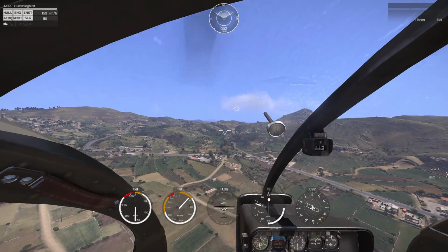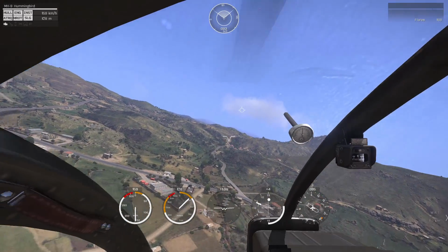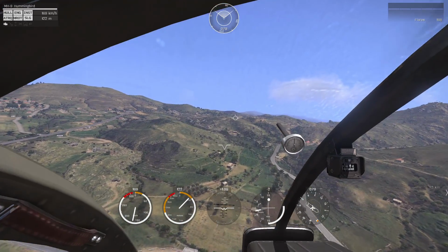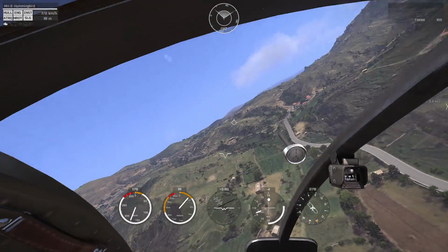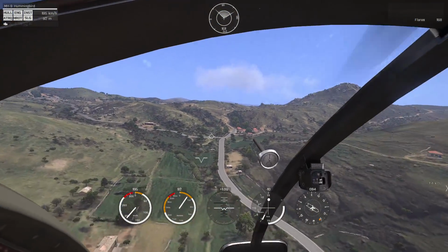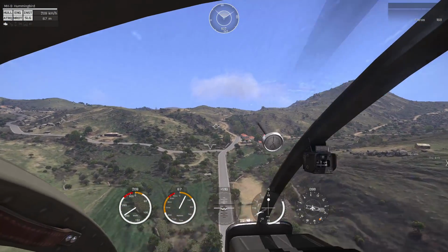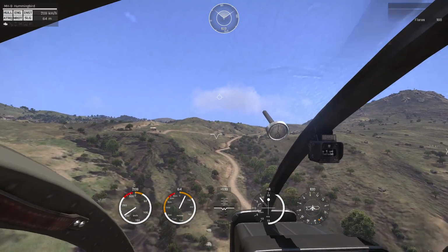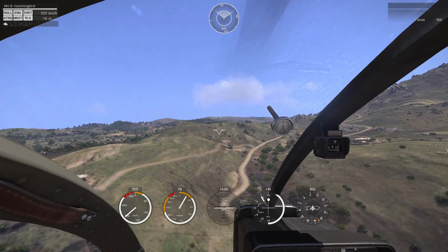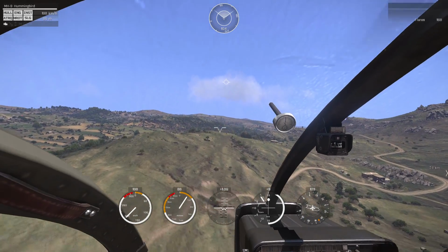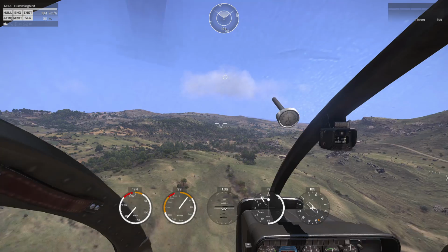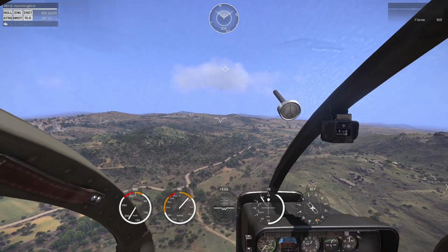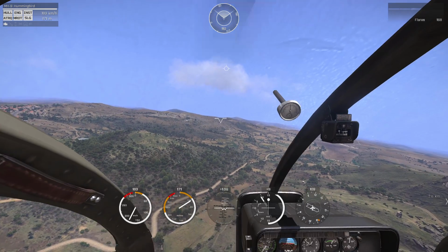So I'm going to move the joystick just a little bit to the left now. So there you go. Now I've moved it about 10 degrees off the vertical axis. So 10 degrees right, and the aircraft moves very quickly. But as you can see, I'm having a little bit of trouble just getting the aircraft to go straight up and down. So I'm going to try and center it so it's straight up and down exactly, and it's very difficult to do. I almost have to rattle the stick to get it so that it's straight up and down.